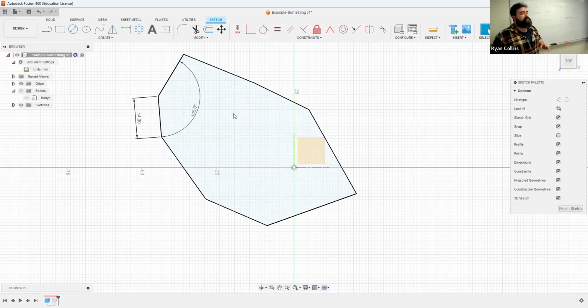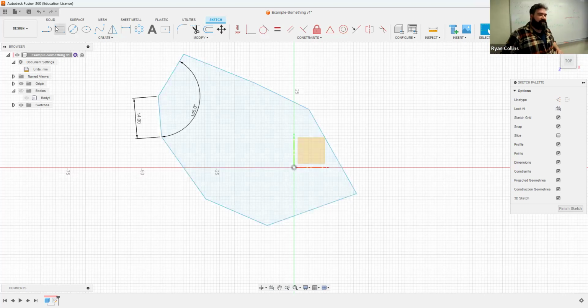So if you eventually want to extrude stuff, which is what we're going to be doing, it has to be a closed sketch for the most part. I'm going to explain that also later. You have a variety of different tools. Obviously, you have rectangles, circles, ellipses, curved lines, and mirror. You also have some modifiers like making patterns and making multiples. You can also alter your toolbar, because I hate that the center rectangle is not by the 2-point rectangle. You can click and drag and move the tools around.